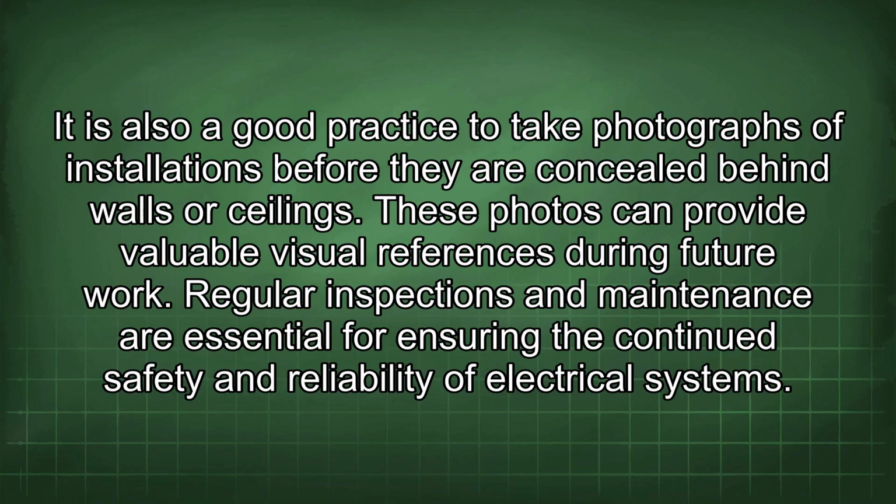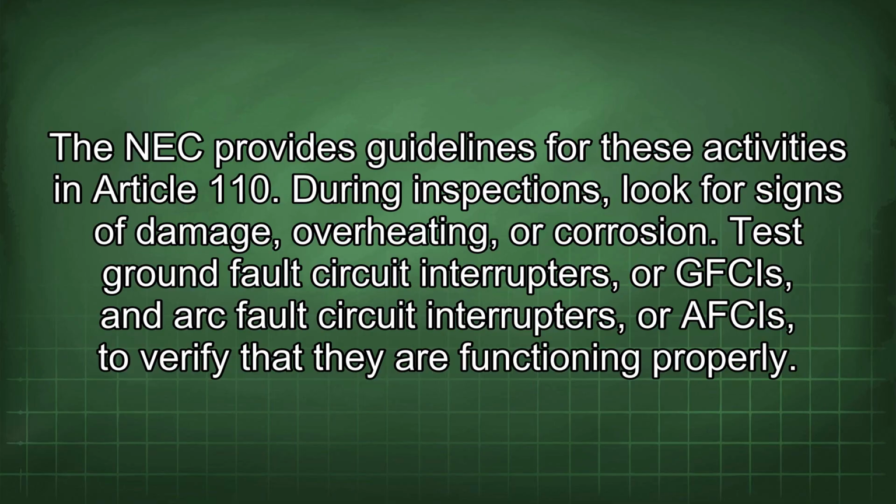It is also a good practice to take photographs of installations before they are concealed behind walls or ceilings. These photos can provide valuable visual references during future work. Regular inspections and maintenance are essential for ensuring the continued safety and reliability of electrical systems. The NEC provides guidelines for these activities in Article 110.